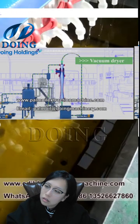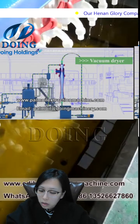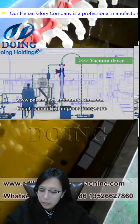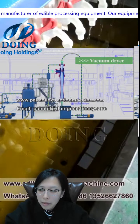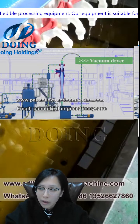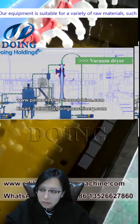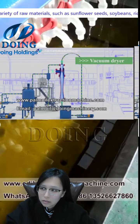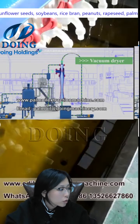So we will give a high temperature, because in the vacuum environment the boiling point of water will be lower, not 100. It will be less than 100, maybe about 60 or 70 degrees, so that we can very easily remove the water from the palm oil. This is our vacuum drying system.